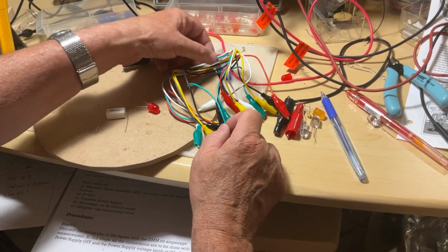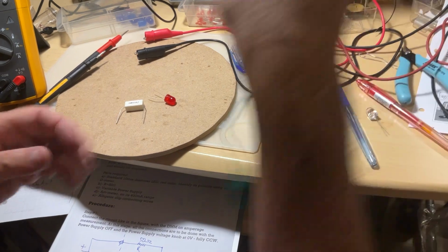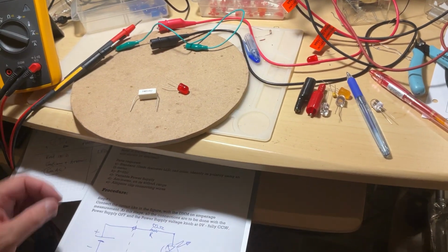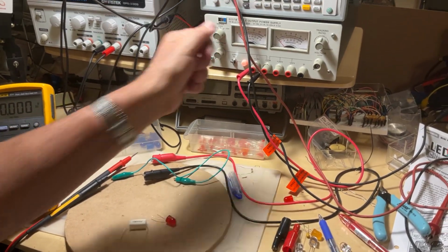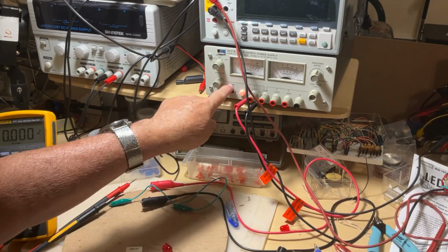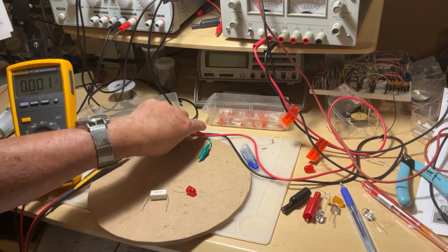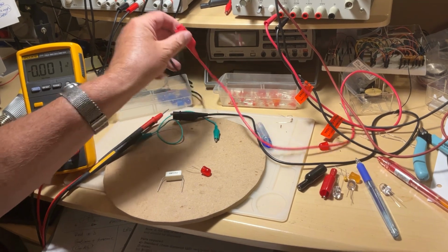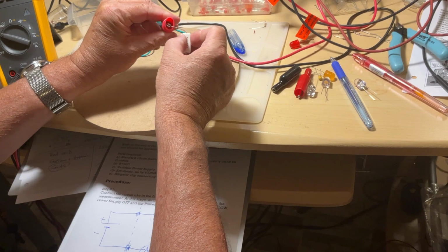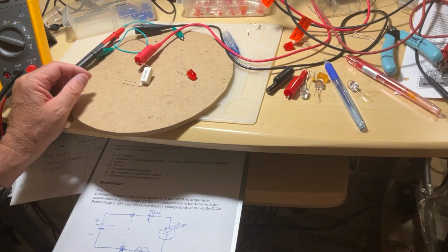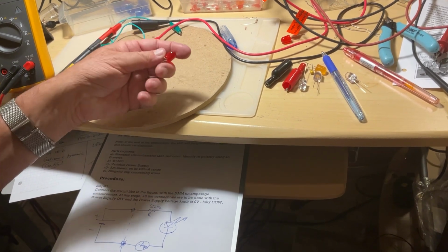Now I'm going to pick up one wire from here. And let's see what we do. To make the experiment right, the first thing you do is you bring the voltage to 0. Connections are made with the power off. So now we pick up the two connections here and we follow the diagram. This is the red of my power supply. I bring it to one leg of the resistor, like that. The other leg of the resistor has to come to the anode of the diode.